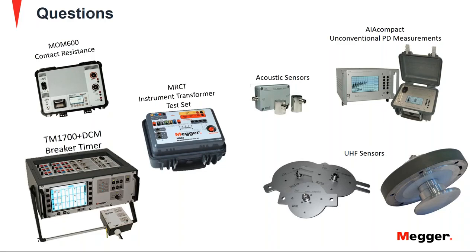Thanks, Michael. Certainly, yes, primarily for safety. And it can also affect certain measurements like ratio. By short-circuiting those secondaries not under test, you can have a reflection on that CT that you're testing. So yes, you want to always short-circuit those secondaries not under test, primarily for safety, and they can also affect certain measurements.